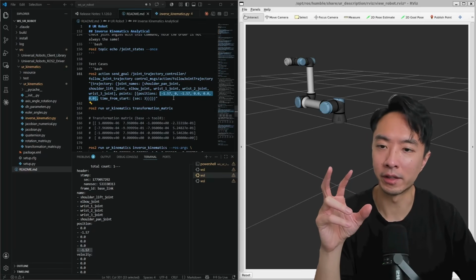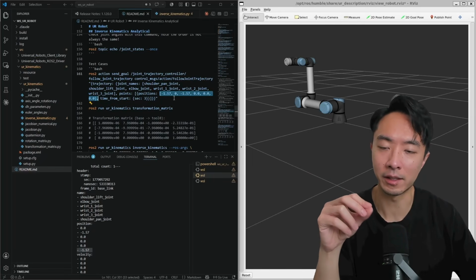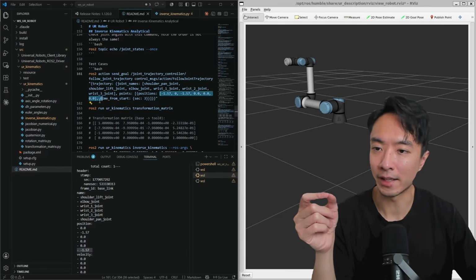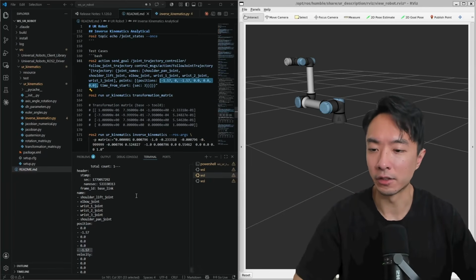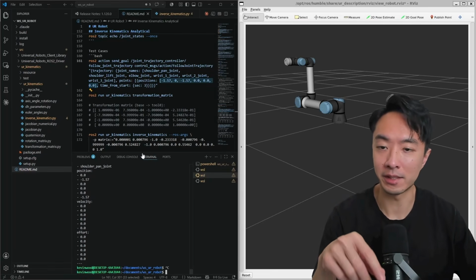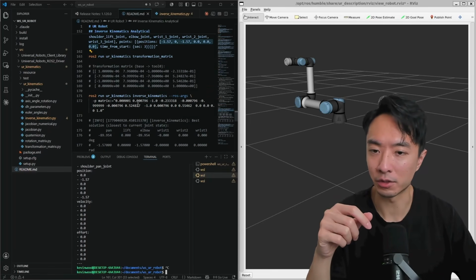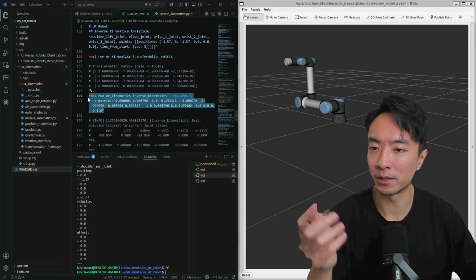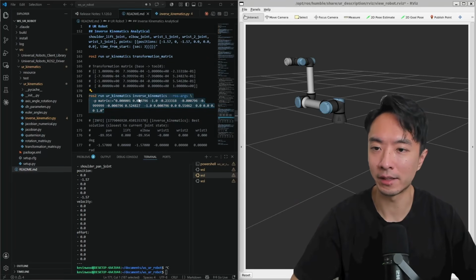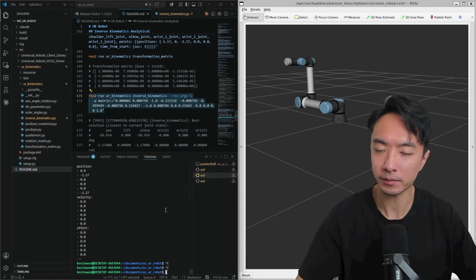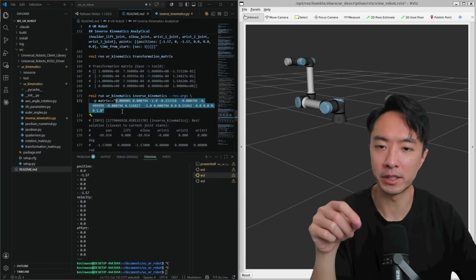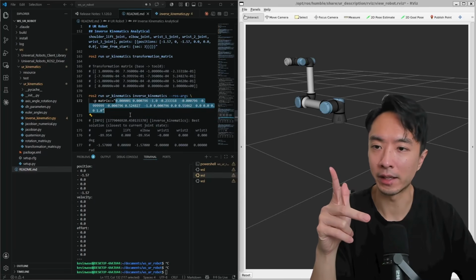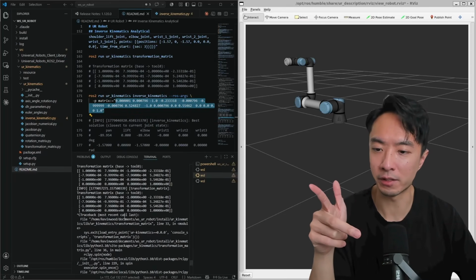But if I run the inverse kinematics, I am going to expect these angles from the output if the solution is correct. So that's some way you could do a sanity check to make sure your solution is right. I have the script here that can check the inverse kinematics. I wrote the inverse kinematics solution, the analytical form, here. What this does is you can pass in the transformation matrix of the tool end, and we confirm that using this printout right here.